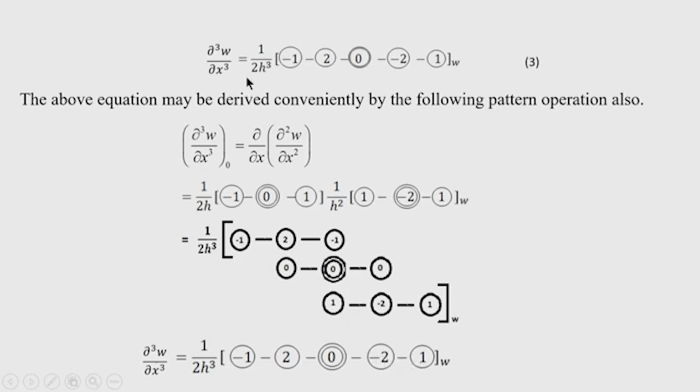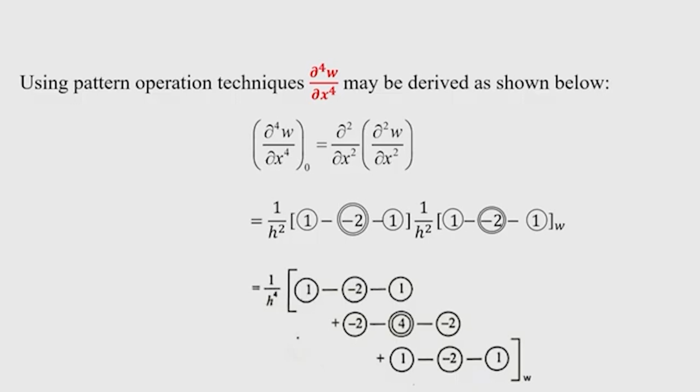So, this is same as this, and you can see here that the antisymmetric pattern is observed. Antisymmetric pattern is obvious here, and it is true because it is a third derivative, an odd number of derivatives. So, antisymmetry should be reflected in the expression. Next we consider the last derivative, because our plate equation is of fourth order. So, we must go up to the fourth order derivative.